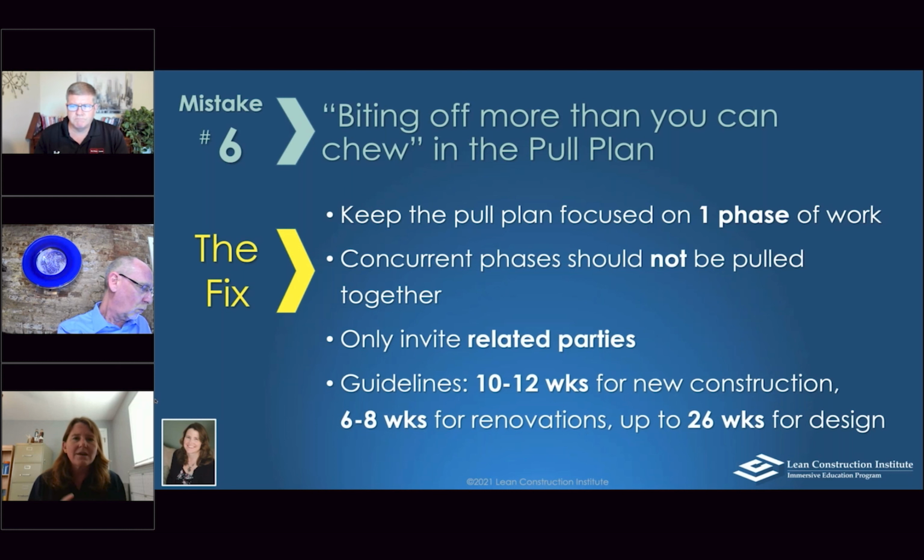And then finally, keep in mind these different rules of thumb for the time frame you're working toward. If you're doing new construction, try to keep it to about 10 to 12 weeks, and 6 to 8 weeks if you're doing a renovation, because they can get a lot more complicated. Twenty-six weeks for design is about how far you can go out, and that makes it manageable for around a 4-hour session that you're doing in your pull plan. So let's move on to number 7.